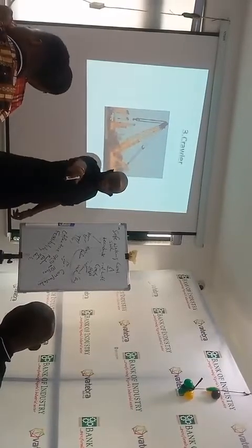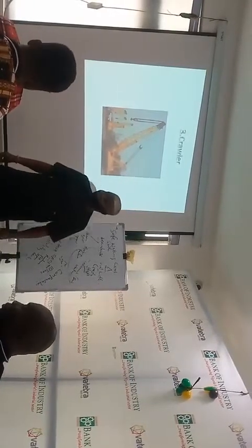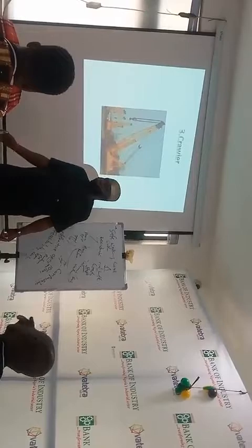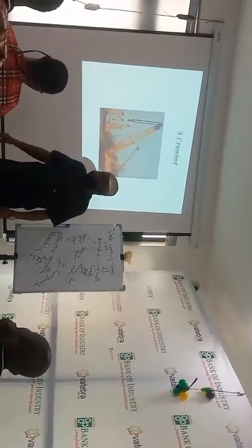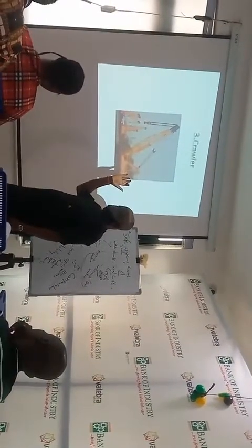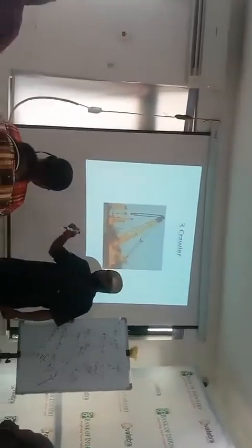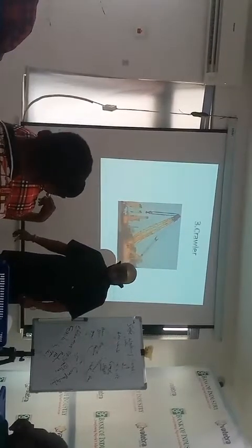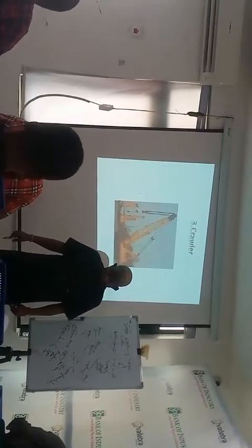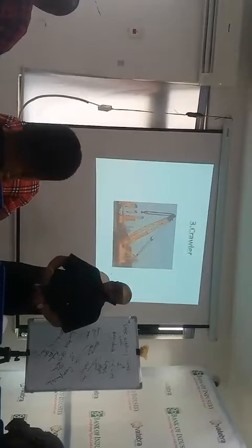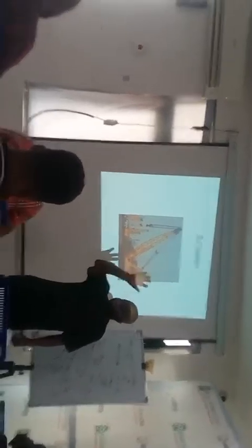You are given a cargo like that bag there now. You don't know the tonnage, and you've not seen the self-weight load of the crane indicated. So you do what we call a trial lift. What you will do is you don't pounce on the cargo. You don't pounce on the cargo.